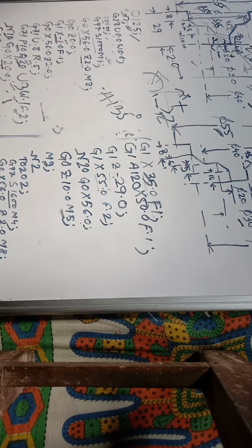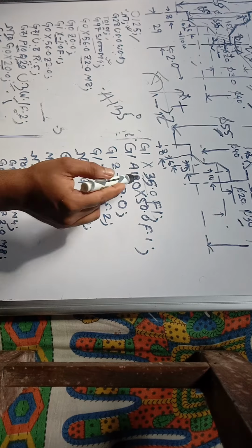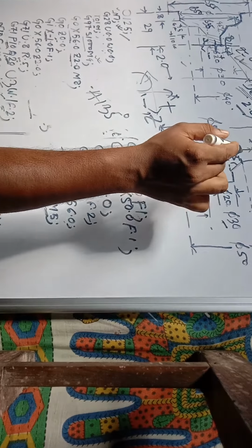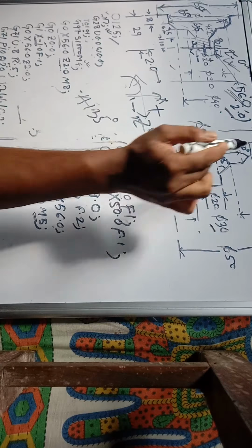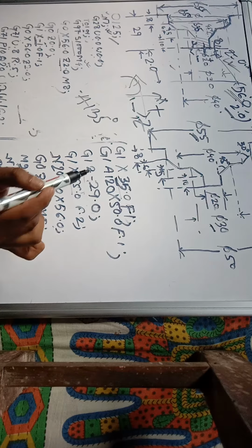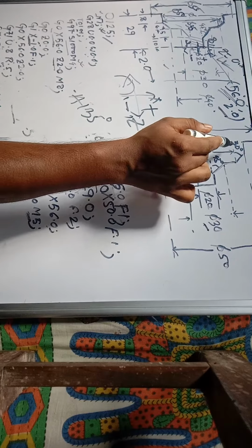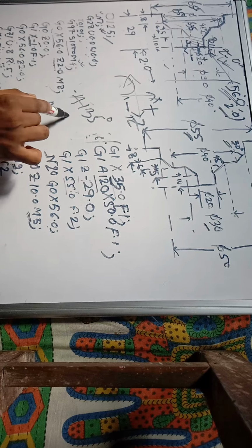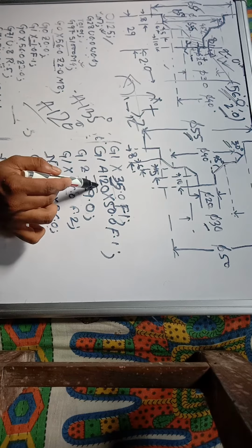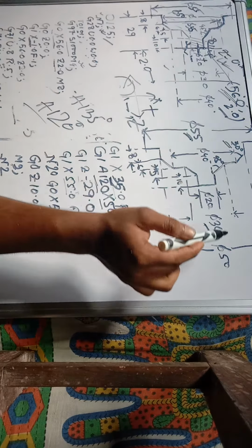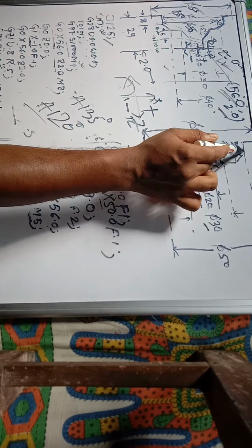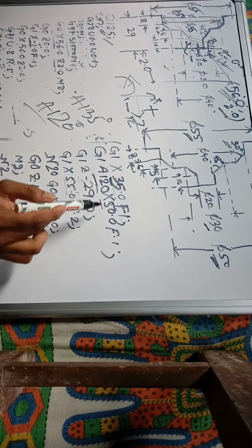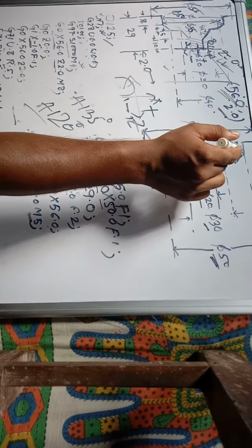After that it will move linearly by means of X35, with the feed of 0.1. After that there is some angle, that is a 30-degree angle. Then what is the value of this angle? It is 120 degree. Simply we put 120 degree with the value of X, that is 50. The diameter given here is 50, and the angle is 120 degree and X50.0.